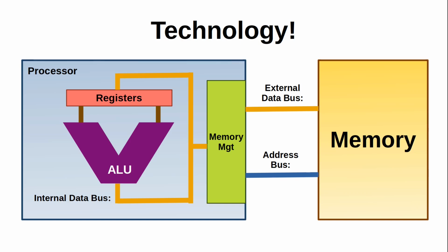And even the most simple 8-bit computers don't have a mere 8-bit address bus, because that would only be 256 bytes of data. That's not a lot of the program or anything to deal with, and you really need to have a wider address bus than your data bus.